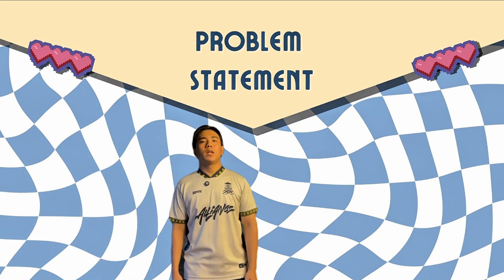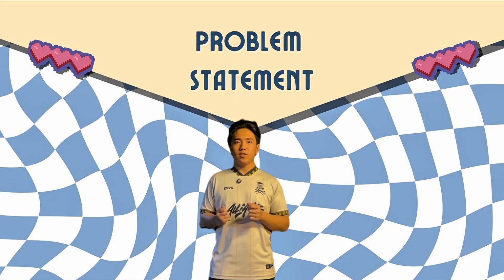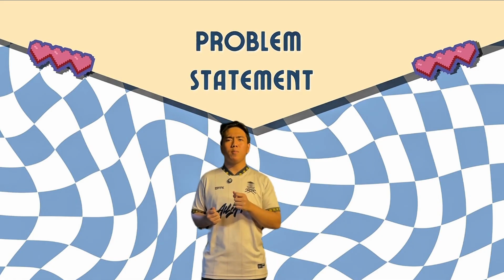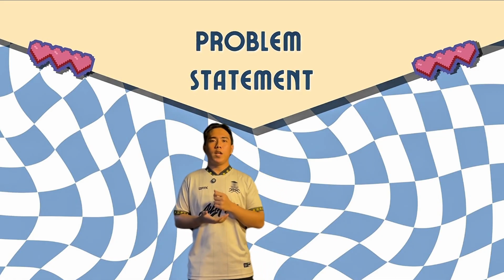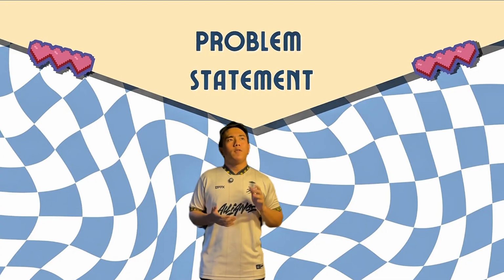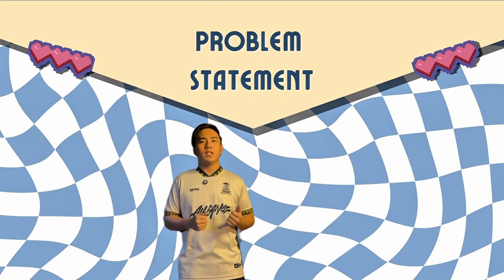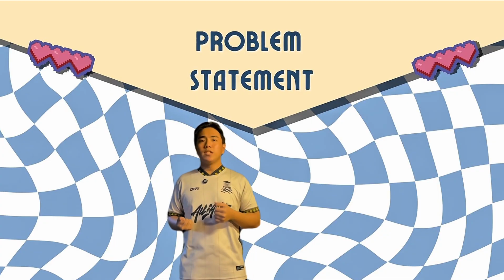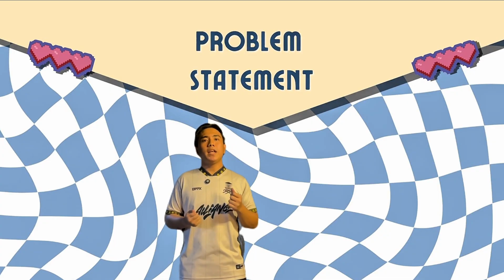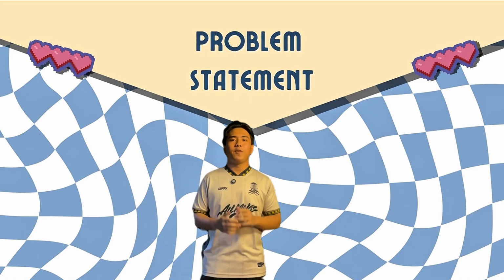One of the problems regarding water gates at dams is reliability of operation, where certain gates would only be used once in almost 100 years during a flood event, thus resulting in corrosion and power failure. Furthermore, debris blockage can happen to water gates, as during floods the river carries trees and sediments, making the gates jam and water rise uncontrollably in the reservoir.